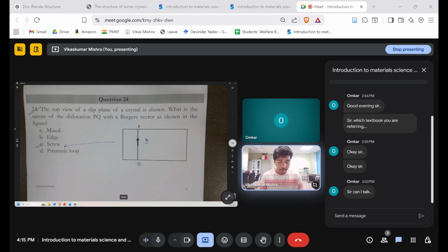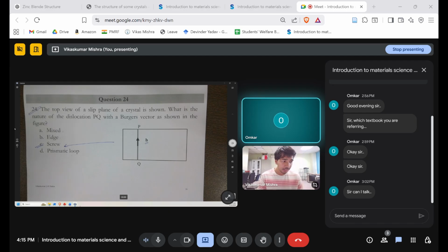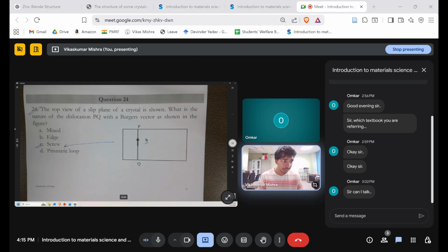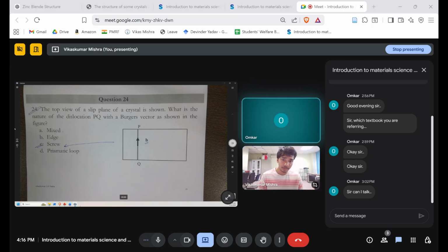Okay, you're talking about the 74% atomic fraction, the vacuum. Yes, sir, that one. Actually, that is something which has already been covered last week, or the week before. So in FCC we got 74%, then in BCC we got 68%, and simple cubic is 52%. You asked how we find that procedure.